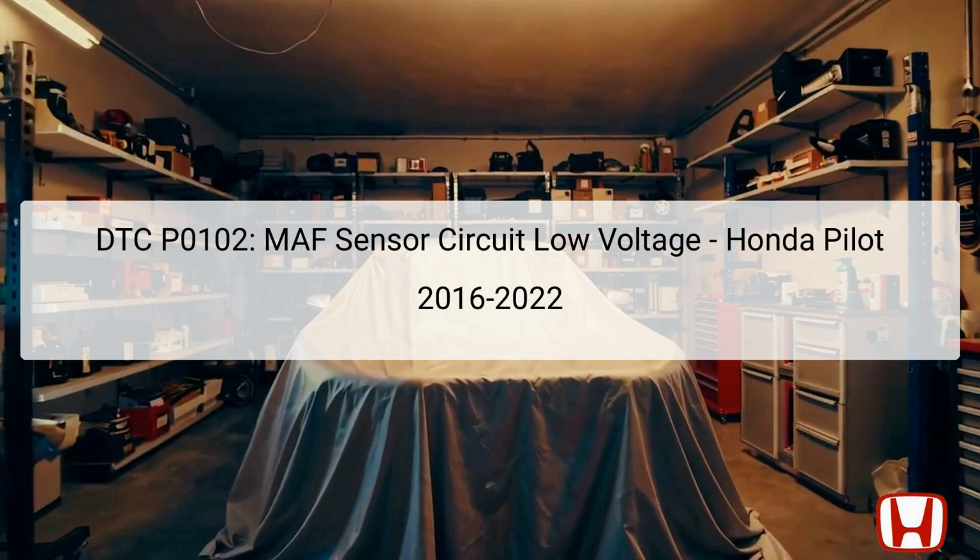Located in the intake duct, the MAF sensor sends real-time airflow measurements to the Powertrain Control Module, PCM. The PCM uses this information to adjust fuel delivery for efficient combustion. When the MAF sensor detects air volume less than expected, it triggers the P0102 code. Identifying and resolving this issue requires a systematic approach to diagnose and repair potential wiring faults, connection issues, or the failure of the MAF sensor itself.